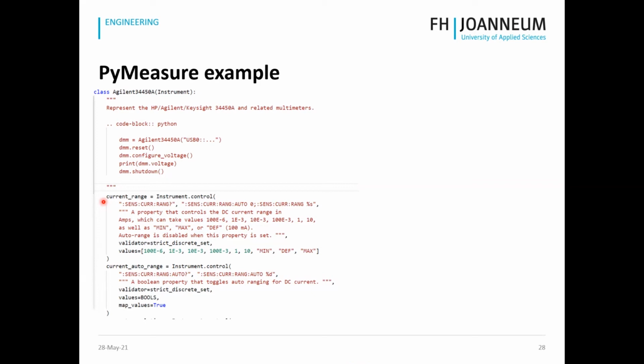Basically all you do is you have this attribute, and you just assign a value to it, and it more or less automatically gives the according SCPI commands to your device and controls it via that, which results in, from my point of view, a very, very nice syntax if you are communicating within your code. If you want to set some values, it's very nice to work with.